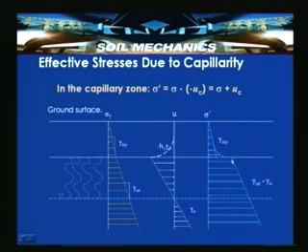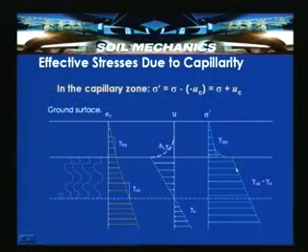So, if you substitute here, then we will be able to get that the net distribution is like this. This shift in increase is because of minus HC gamma W, which actually gets added to this effective stress. So, it is nothing but the total stress. So, sigma dash is equal to sigma plus gamma W HC at this particular point.